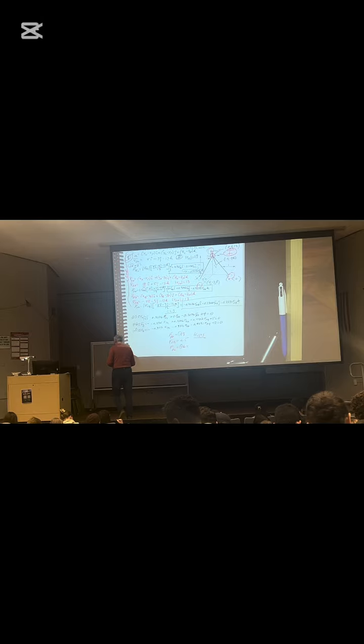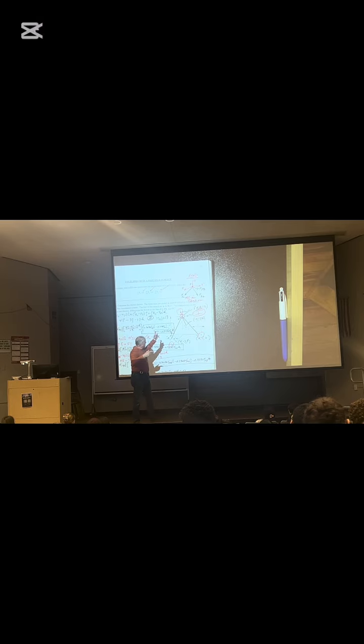Based on the way I drew my free body diagram, my free body diagram showed pulling, pulling, pulling. These are all in tension. Okay? Because they're negative, that means reverse the arrow of the PA and PC, which means they got to push. Once they're pushing on a joint, that's compression.